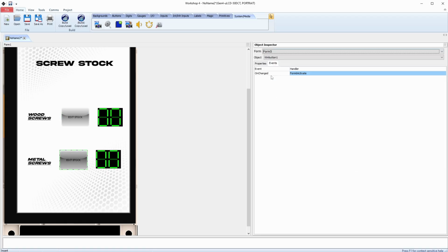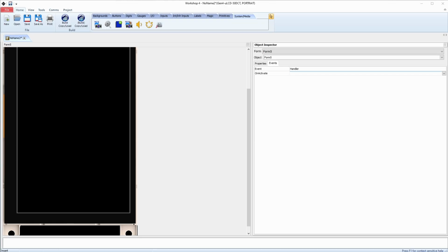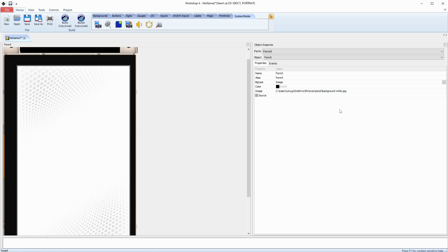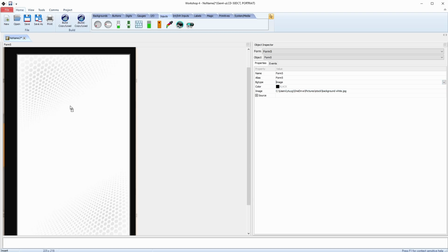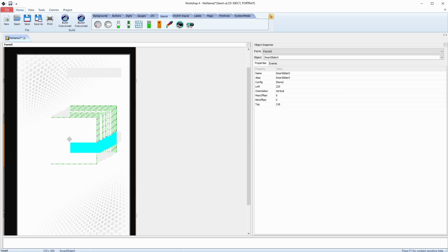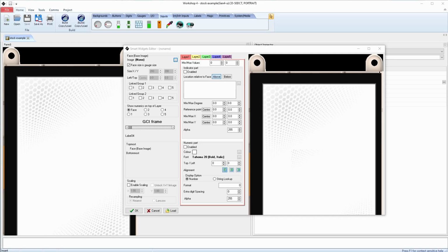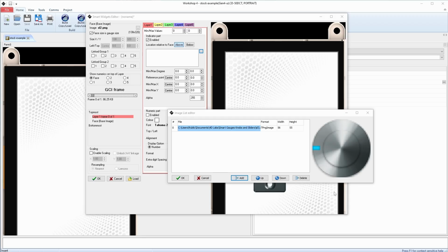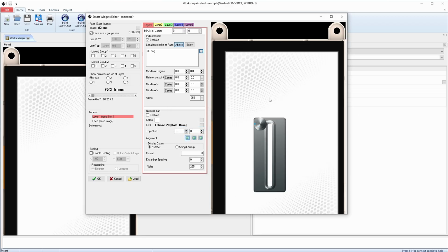Now here's where we're going to build our slider, which will control the digits back on the list screen. All of these graphics will be available with the project file in the video description. What I'm going to do is drag in a smart slider. The first graphic is this base image of the gauge. Then on layer 1, which is above the base image, I'll add the graphic of the knob. Align its reference point to the middle, and I'll make sure its value is 50.